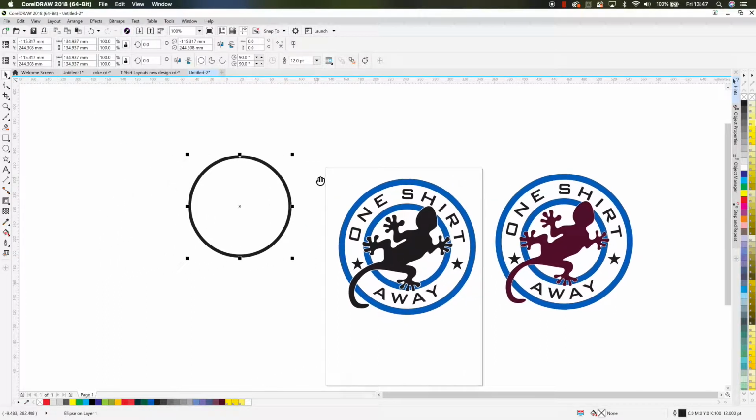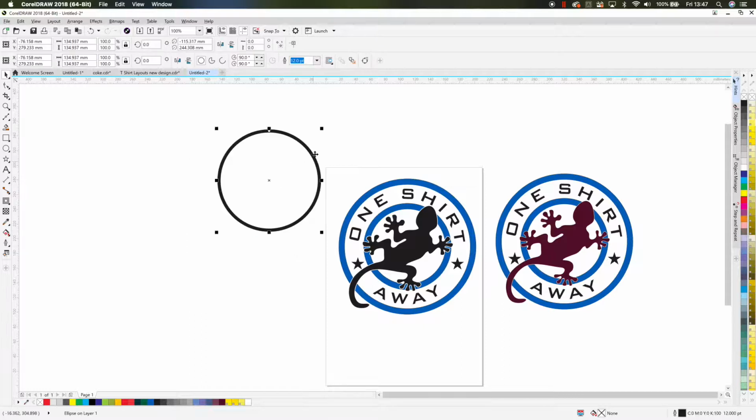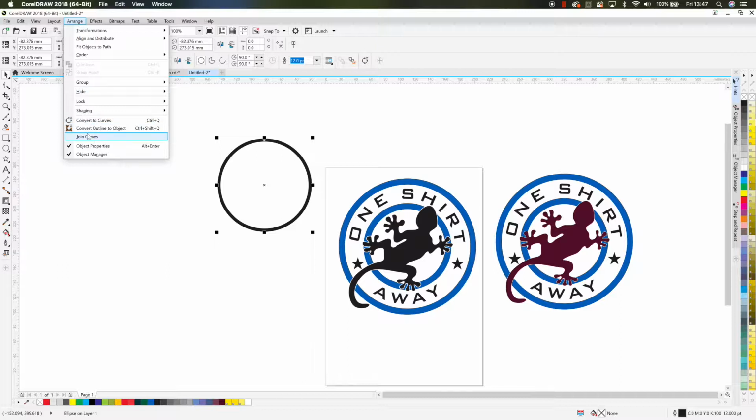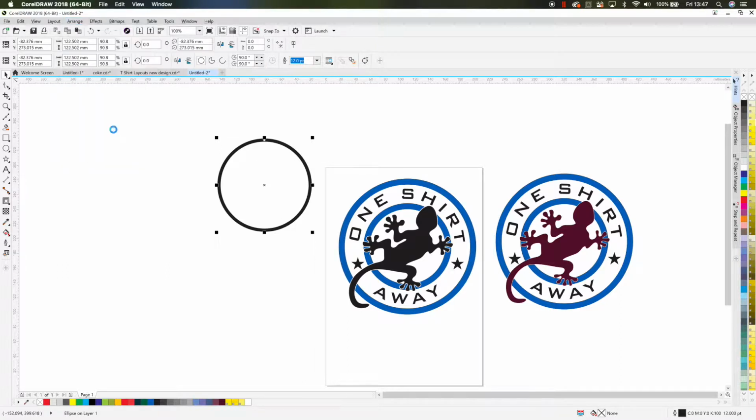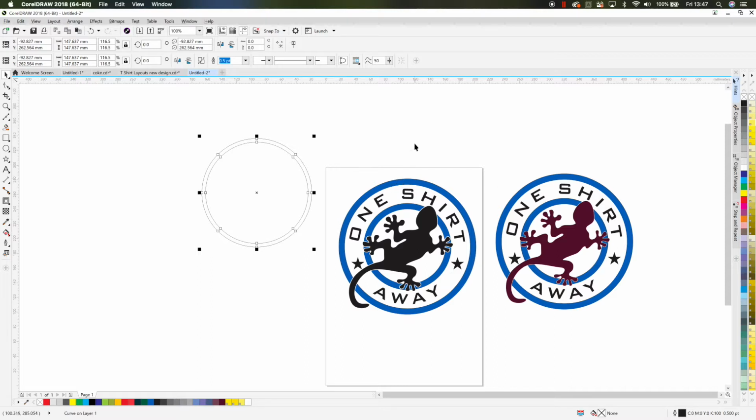Now to make sure and ensure that this is scalable, and so you don't trip up with customers, this is only a 12-point edge at the moment. If you blew this up to meter wide, it would appear like a very fine black thin hairline, and it wouldn't retain its thickness. So if you are going to scale it, and the customer has sent you artwork, and the outline, you notice when you reduce it, appears to become thicker or thinner, go to the Arrange tool and select Convert Outline to Object. So if I do that, I click on that, it has now become an inner circle and an outer circle that are combined. So if I come across to the Fill tool and select No Fill, and then right click with a black, you can see that we've got the same component that we got when we made up our circle on our gecko logo.